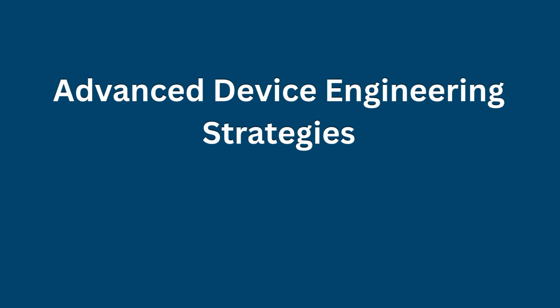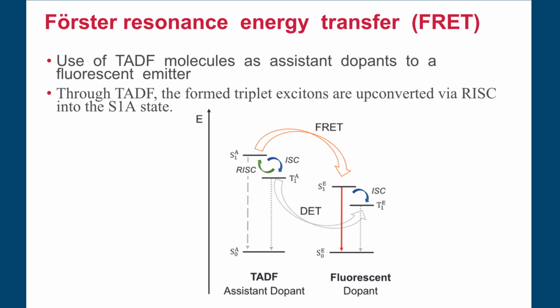Advanced device engineering strategies. Sensitized emission, hyperfluorescence. To overcome the limitations of TADF emitters, sensitized systems decouple exciton harvesting and emission. TADF or phosphorescent sensitizers transfer energy to fluorescent emitters via Förster resonance energy transfer, FRET, improving efficiency and color purity.